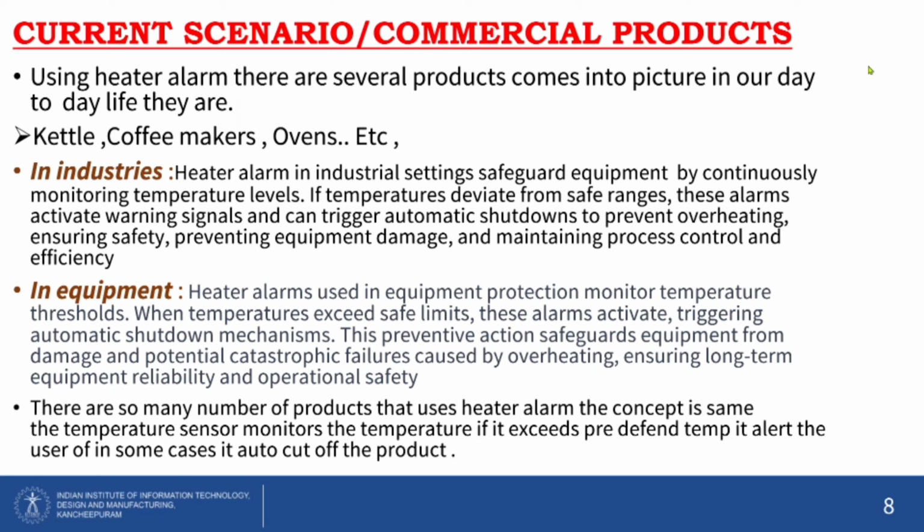These actions safeguard equipment from damage and potential catastrophic failures caused by overheating, ensuring long-term equipment reliability and operational safety. Heater alarms are used in equipment protection by monitoring the temperature threshold. When the temperature exceeds safe limits, these alarms activate, triggering automatic shutdown mechanisms.